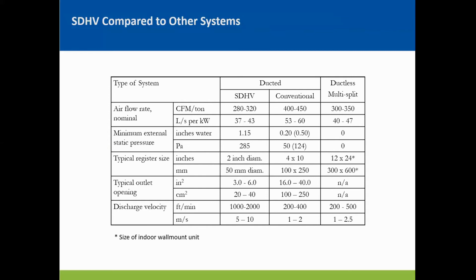Right now, it's a range between 0.1 and 0.3 inches of static pressure, depending on capacity between 1 and 5 tons. The same with the small duct high velocity. It's also a range which is 1 inch greater, 1.1 to 1.3. Starting in 2023, the Department of Energy, in an effort to mirror what you typically see in the real world, how they're installed, has raised the conventional external static to 0.5, and it's without any range.